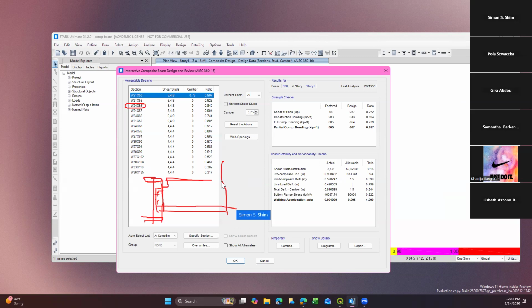The beam is 21 and the girder is 24. In this case, we maybe don't need to cope all the way through the web. Probably we only need to cut the flanges here, because the vertical web can go straight down, back to back of the shear tab. So only if we can cut these flanges. If they're using other bolted angle connections, let's say.